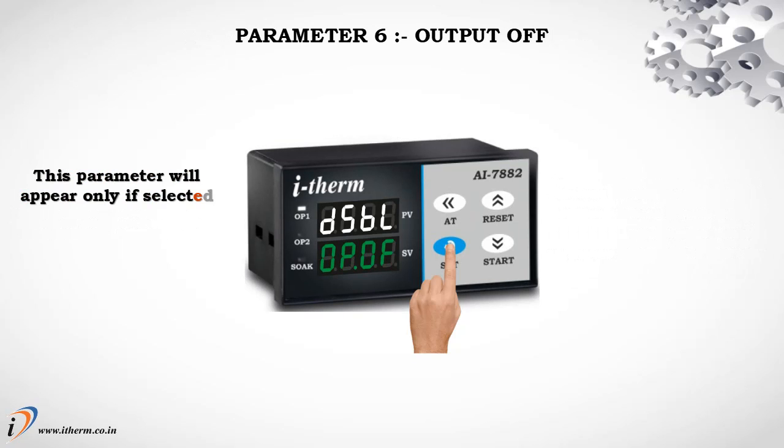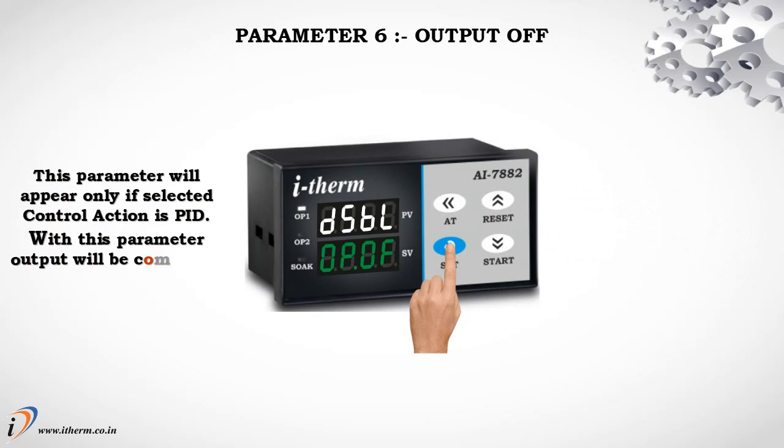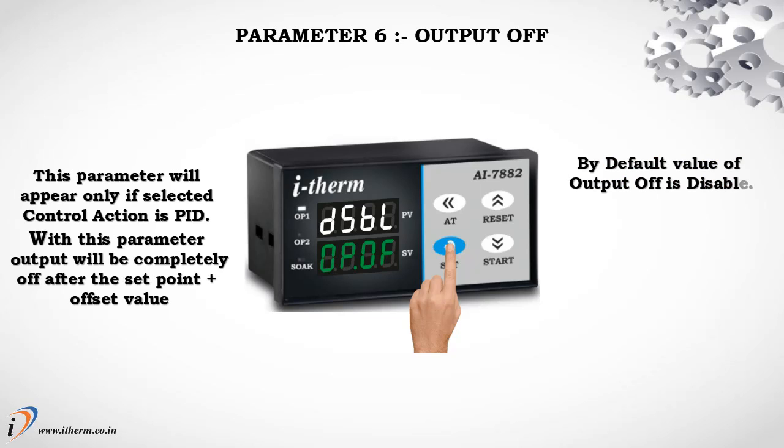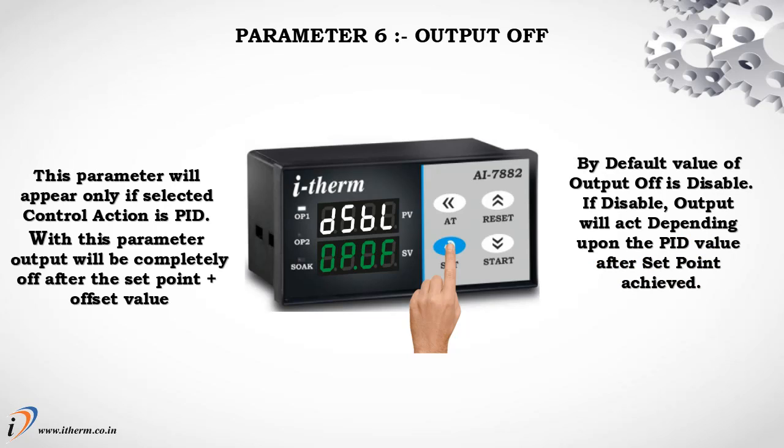Parameter 6, Output Off. This parameter will appear only if the selected control action is PID. With this parameter, output will be completely off after the set point plus offset value. By default, the value of output off is disabled. If disabled, output will act depending upon the PID value after the set point is achieved.